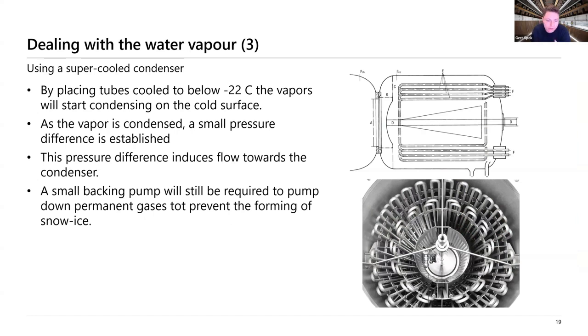If you consider an environment where the air has a certain vapor pressure of water vapor introduced in the pipe, this will of course cause a pressure drop near the condenser where it removes this pressure again, and then induces a flow, a pumping flow as it were, to move this water vapor towards the condenser.